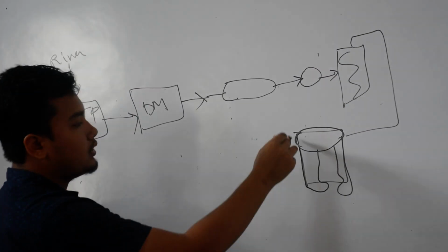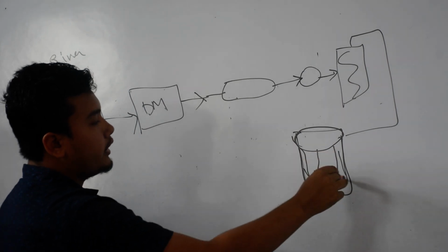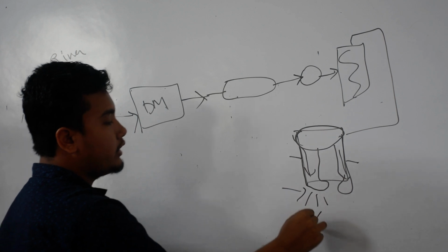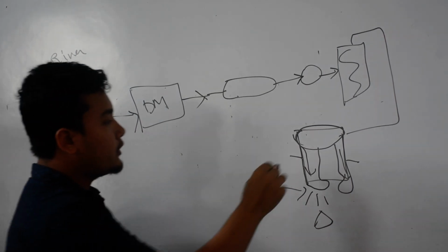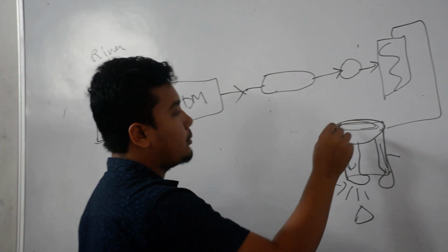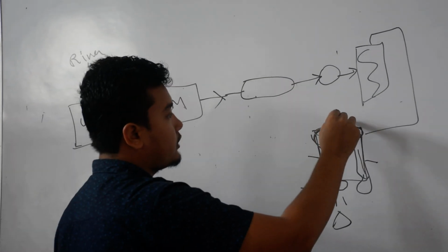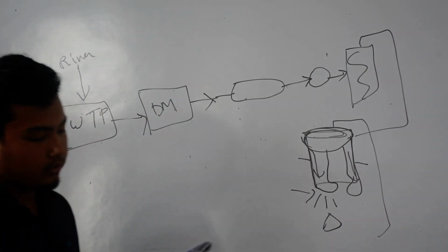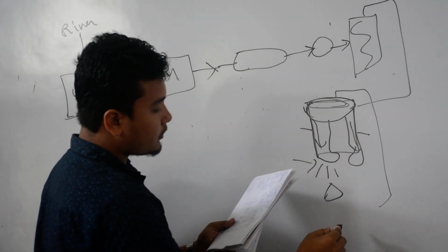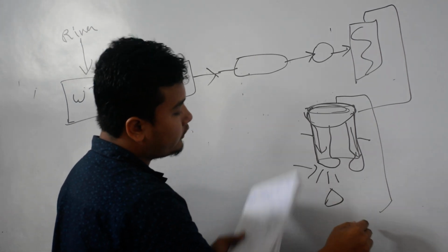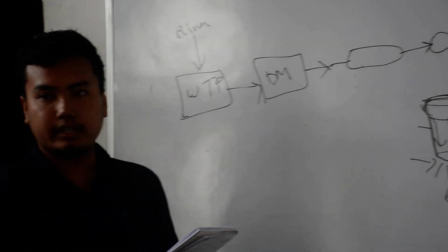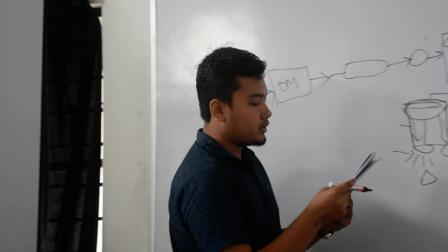In the water tubes, water will be dropped, and here the water will be heated by giving air and heat. From there steam will be generated, and it will be stored on the top. From the top, the steam will be taken through tubes, and it will go to the convection superheater. In the convection superheater, the steam will be heated, and it will be taken to the desuperheater.